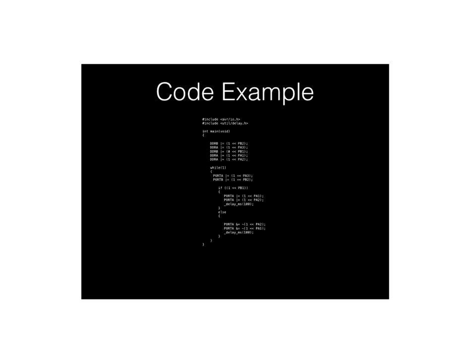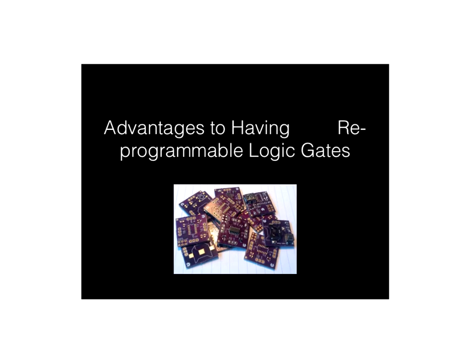Okay, so our code example for an inverter basically runs on an AVR microcontroller, and here it sets out what pins are being used, and here it's detecting if there's an input, and if there is, turn the pins high, or if not, turn it low. We used an AVR ATtiny24A, which is a low power microcontroller from Atmel.